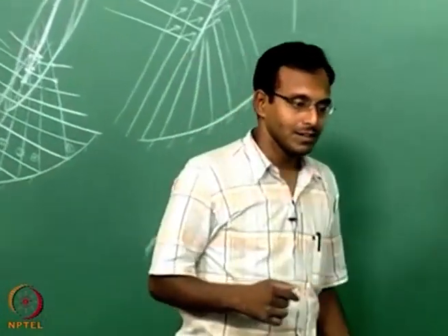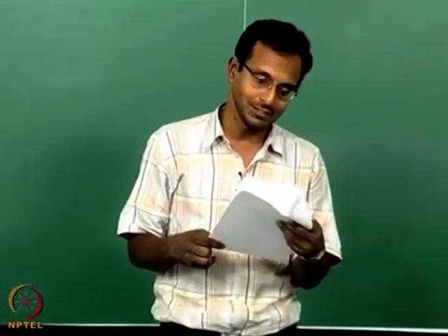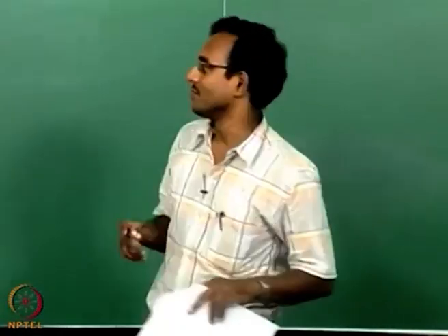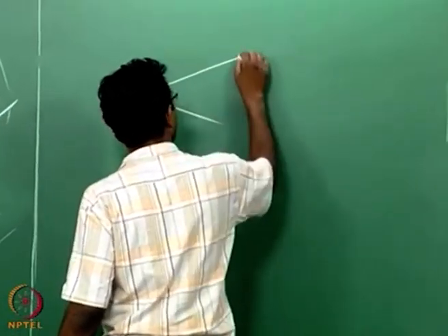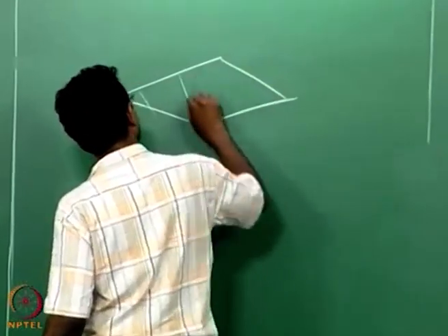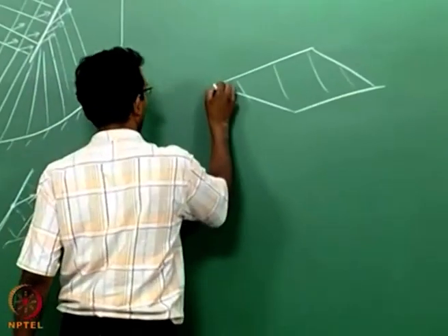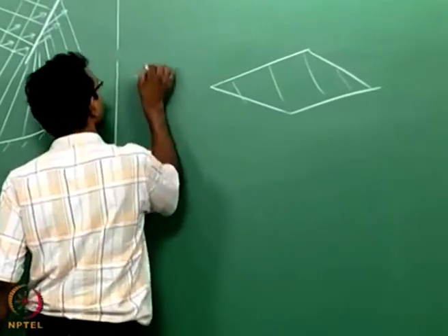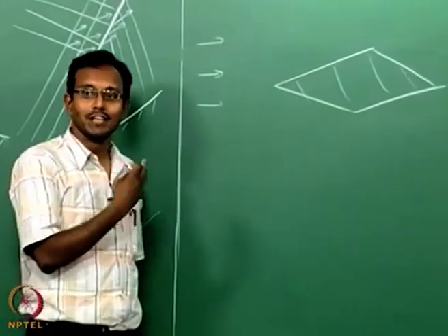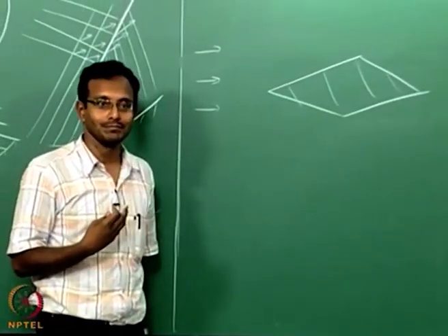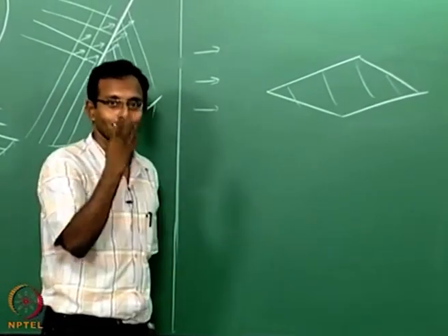Okay. But if I am given a flow over a body, kind of external conditions, then how will I solve the problem? Say I have a situation where I have some diamond shaped wedge airfoil and I have some supersonic flow, parallel flow incoming. Do I need to give you initial conditions for this problem? Initial line, it is already given when I said parallel flow, uniform Mach number.